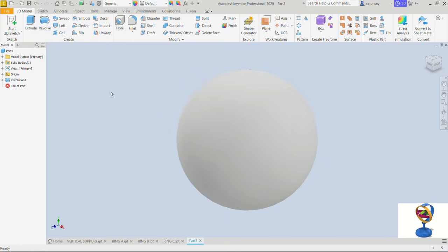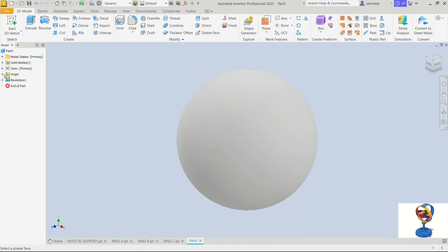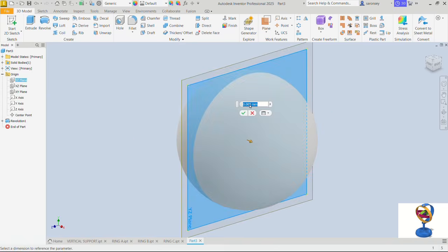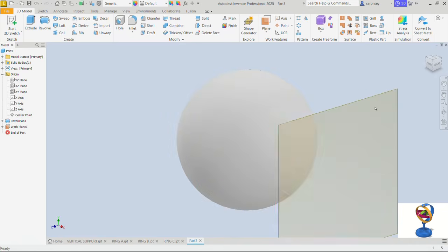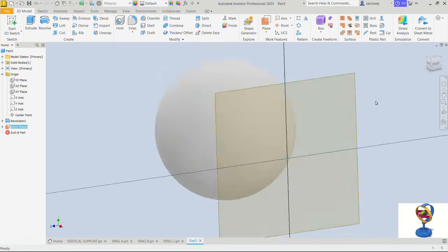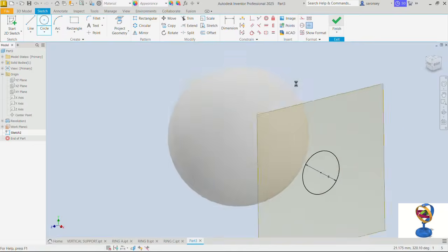Let's create the rods for mounting it. For that, let's offset a plane to, let's see, open up the planes. Let's pick the YZ plane. The offset distance for this, let's do 75 divided by 3 and check that. Now on this plane, we would create a sketch. Let's draw a circle from the origin of diameter 8. Let's enter that. Now we would finish this.